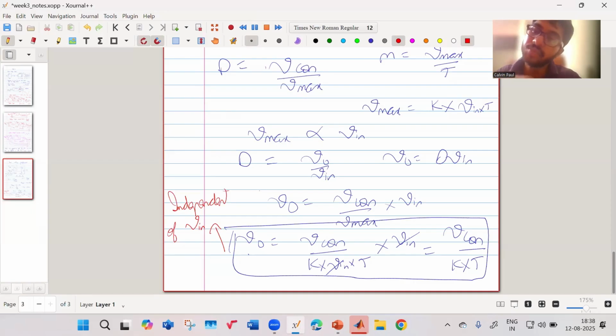Whenever there's a change in input voltage, it is reflected in the duty, which also gets adjusted accordingly. That is known as input voltage feed forward, and this is also used a lot. It is used in power factor correction circuits, where we want to maintain the inductor current in phase with the input voltage so that we can get unity power factor. There they have to use input voltage sensing.